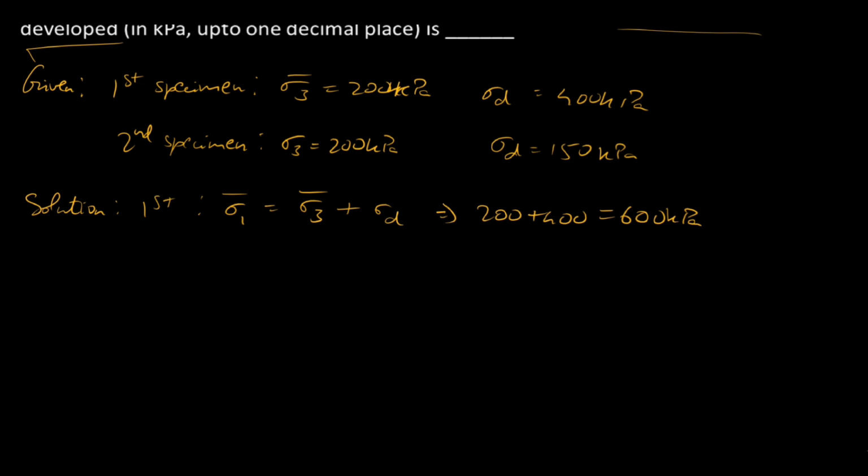For the second one, we can get the total triaxial stress: sigma 1 is equal to sigma 3 plus sigma d, which is 200 plus 150, 350 kilopascal.